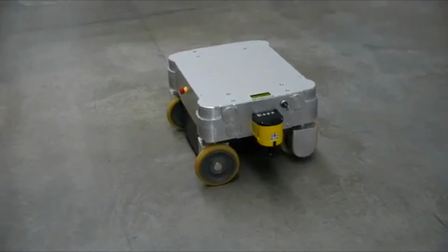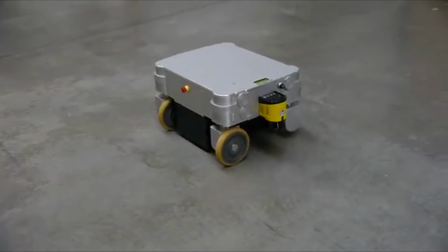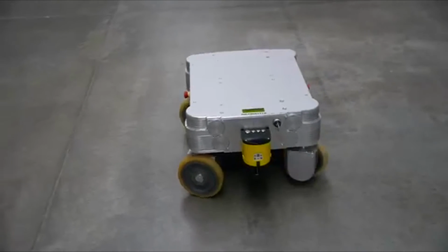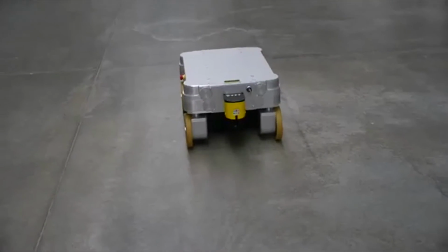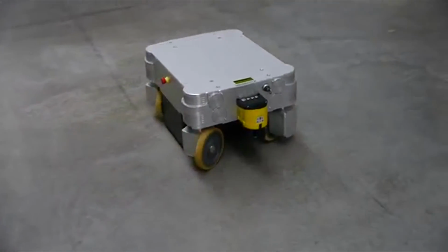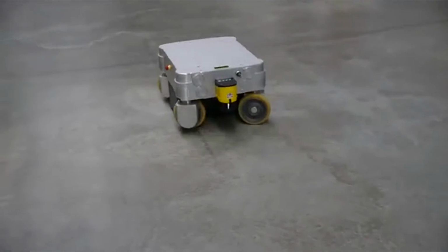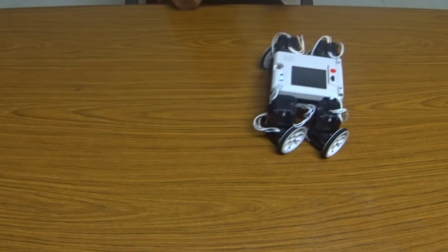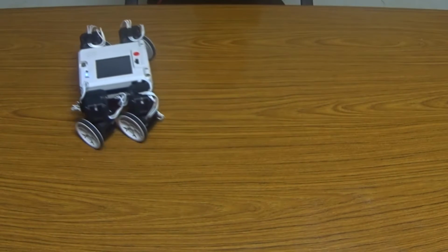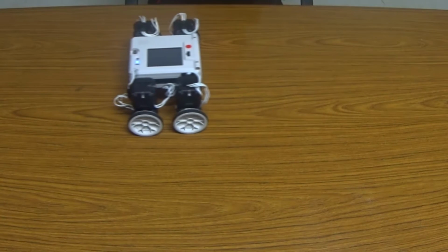Another way to achieve omnidirectional driving is by shifting all the wheels of the robot to face the desired direction. Besides moving forwards and backwards like the other drive systems, the robot can now move sideways, diagonally, and even turn on the same spot, by simply changing the direction of the wheels. This method requires more motors, but it can operate using the conventional wheels.